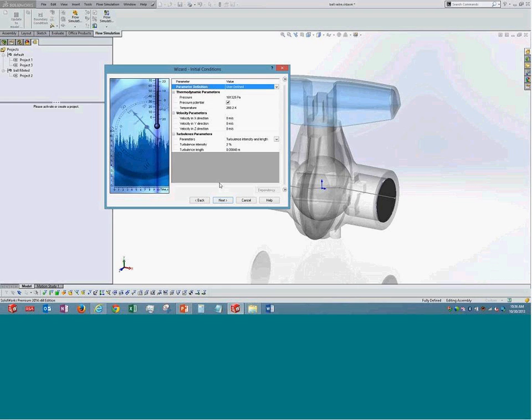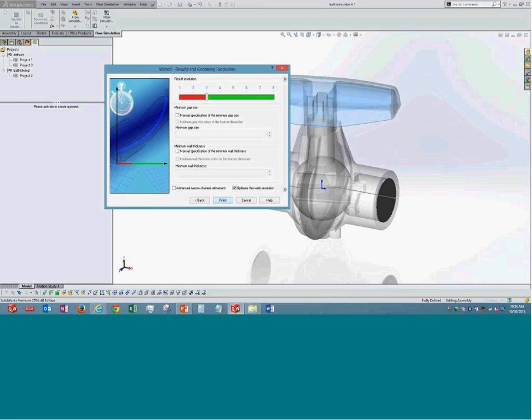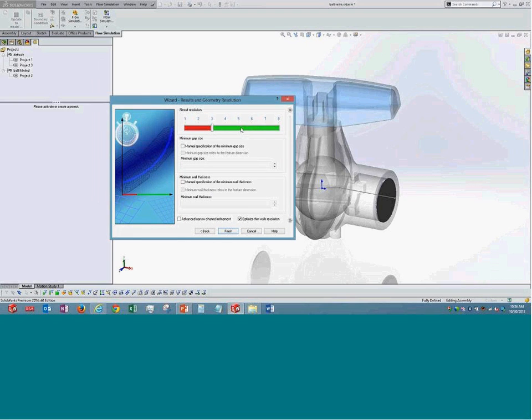It is the mesh quality. This software can by default help us create the mesh using these bars over here. The range from 1 to 5 is more towards mesh refinement. It will refine the mesh more and more based on these particular settings. The most advisable one is the default one, and it creates an optimal mesh. If necessary, you can refine it further. And from 6 to 8, I would say it is more towards the convergence of the different parameters. It is going to tighten the convergence parameters, and we should be able to see more accurate results here.